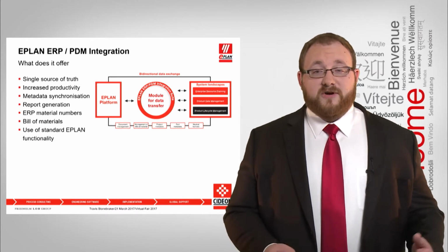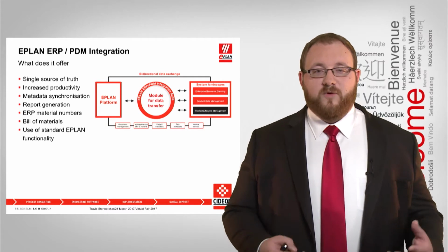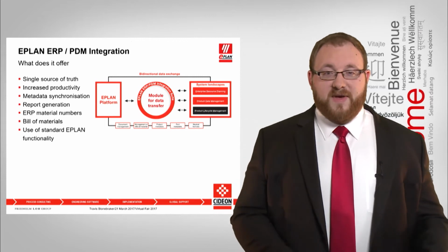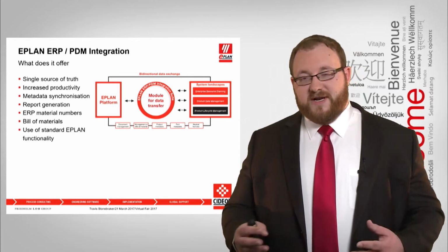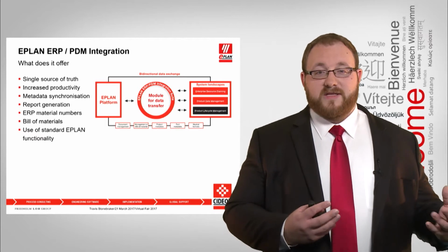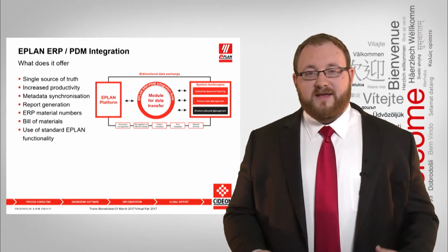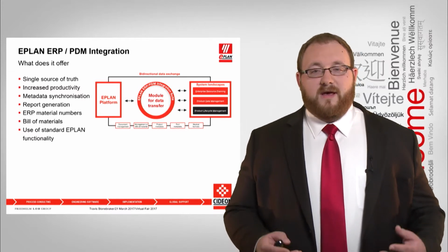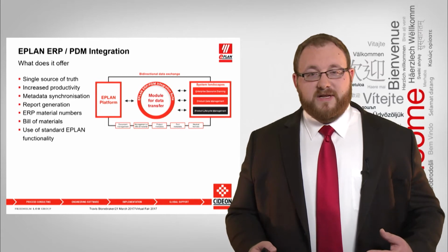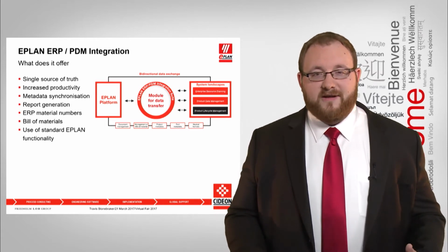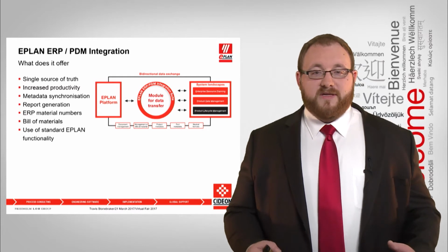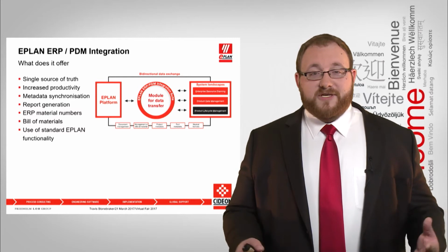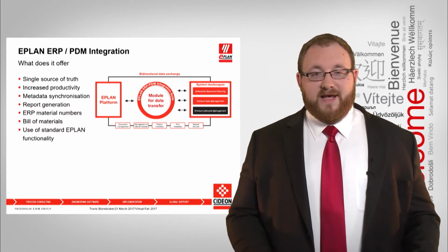Once ERP numbers are assigned, you'll be able to build a full bill of material. Instead of being on a piece of paper or an Excel spreadsheet, or trying to take a report from Eplan and then manually add it into the system, it'll be able to build automatically and then be used for sales BOMs or any other type of BOM applications. What this also means with this integration is that it uses all the Eplan standard functionality. So this report generation, this metadata synchronization with a PDM integration, everything is just basic Eplan functionality at the end of the day.